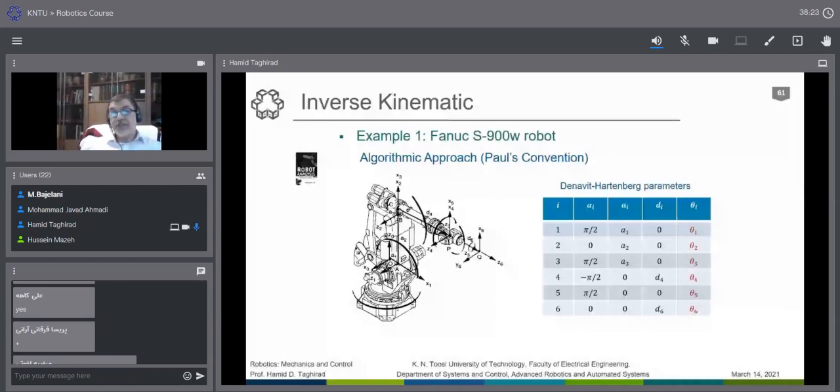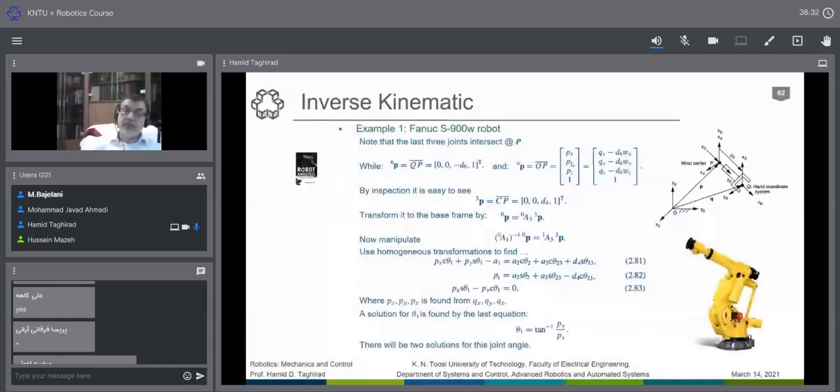Consider that we have this from the end effector. Now we are coming from the base to here, and then we would like to make these two equivalent and find the inverse solution. Now, if you have this given in the third frame, you can easily find it in the 0 frame by multiplying it by the homogeneous transformation, T3 with respect to 0, which is A0 to 1, 1 to 2, 2 to 3, and which we have given here.